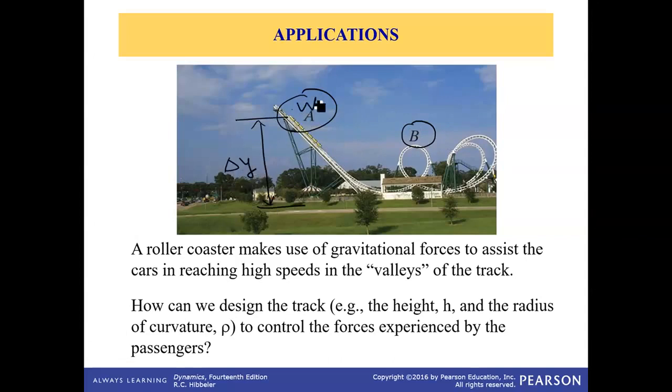So depending on the weight of the coaster, the work done by gravity is positive, W multiplied by delta y. Now, in order for the coaster car to complete the loop at B, it must have a certain kinetic energy at B, because if that kinetic energy is not enough to overcome this loop, then the coaster car may not complete the loop and may just bounce back from a certain height.